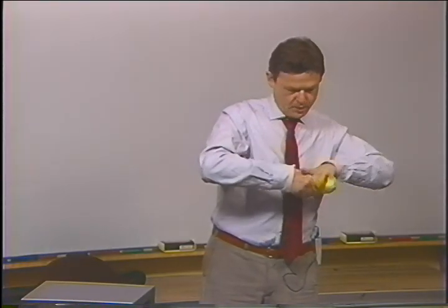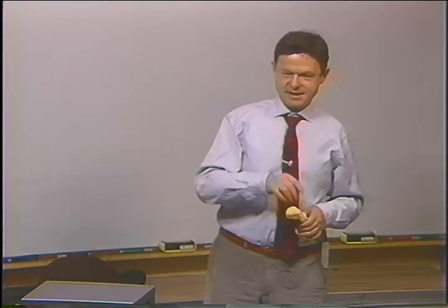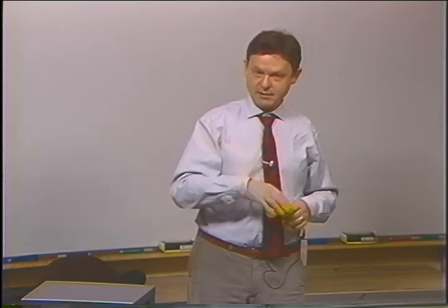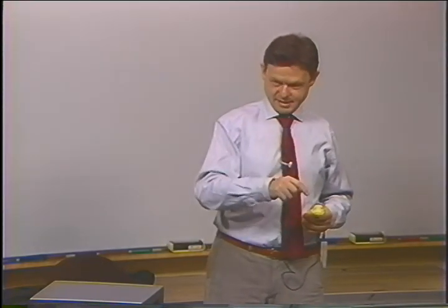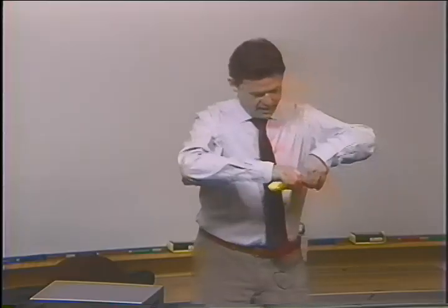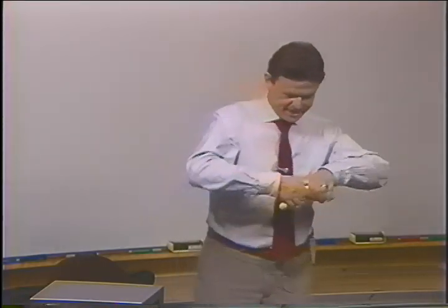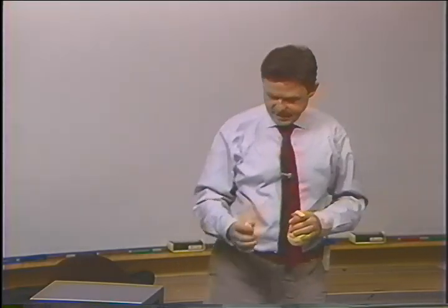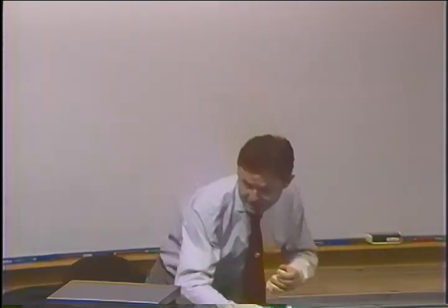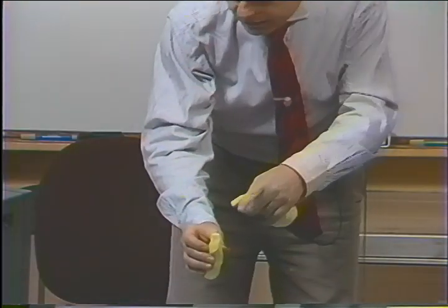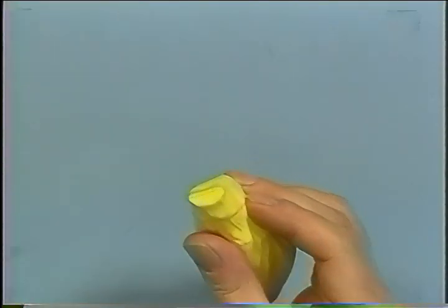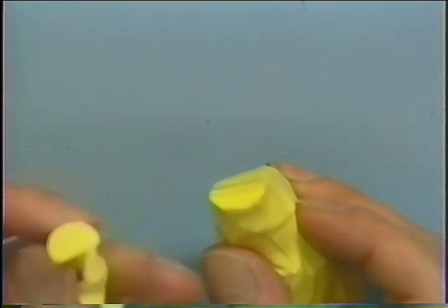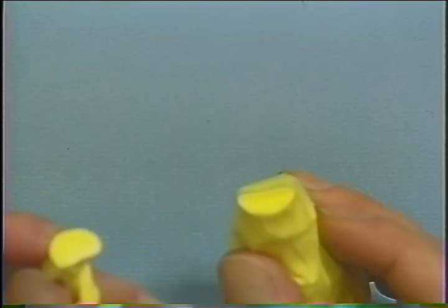And now I want to go to the higher frequency behavior, to the glassy behavior. And for doing that, I will deform this material even faster than during the impulse, which I just demonstrated to you. And since I'm very strong, I can do this. So I'm deforming this, and if you maybe focus the camera on the face here, can you magnify this even further? When you look at the surface, it breaks like glass, the material.